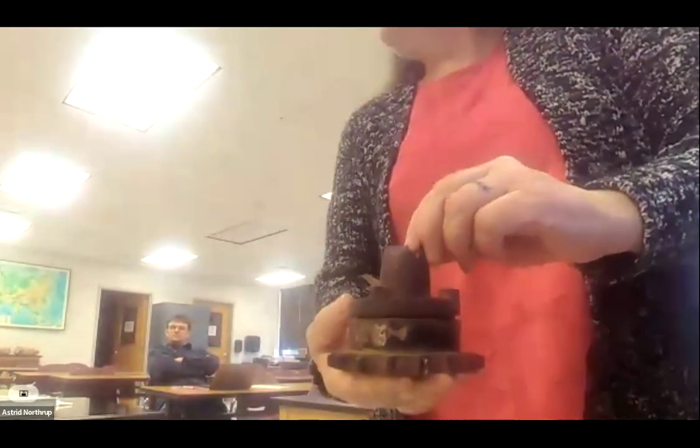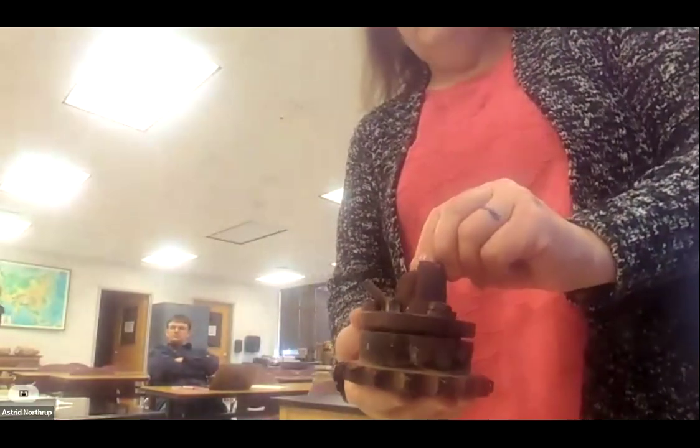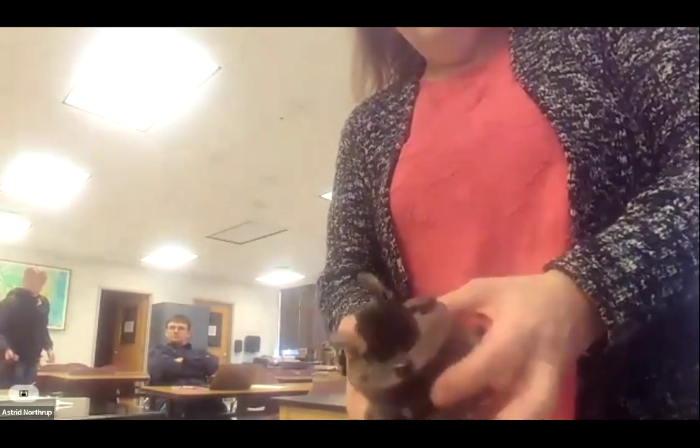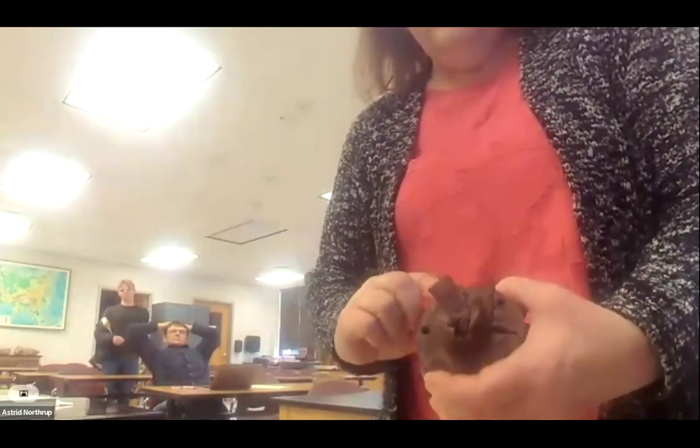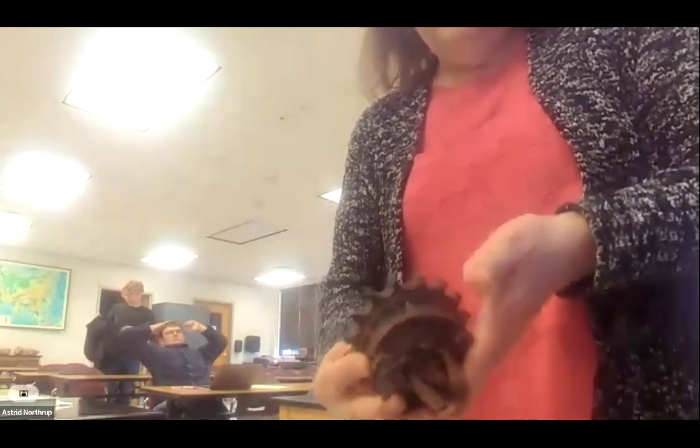So the last thing I wanted to show you, I'm just going to come up here to the camera and see if we can show this. This is what we were looking at. This is a gear that kind of blew up, as you can see. But what happens is there is a drift key right here. This was supposed to fail, but for whatever reason, somebody replaced it with something quite strong. So instead of the key failing, the whole thing failed. So you can see the splines are torn up. We have a break right here where this bolt is, and the whole thing is a piece of junk, but it's a piece of instructive junk.